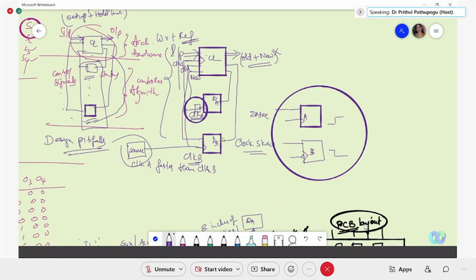The clock source is the same, but this one is sensitizing for the clock going from 0 to 1, whereas this segment will be sensitizing for the next one. That means, if you take the total clock from 0 to 1, your A will be sensitizing the new value of this path, and the 1 to 0 transition of the clock makes the new input to be sensitized by B. That means there is a lapse of this duration.